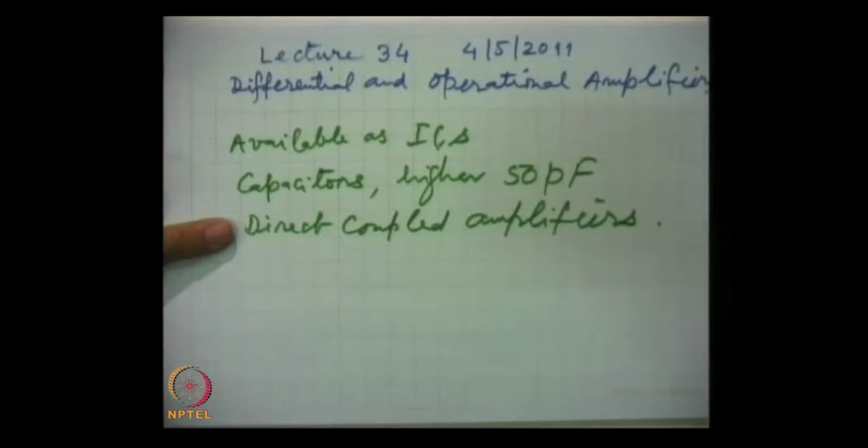And direct coupled, where for coupling just a direct conducting path connects the source, for example, with the amplifier, no need of a coupling capacitor, and hence the frequency response obviously will be different. There is no restriction on a smaller frequency. These amplifiers will work at as low a frequency as 0, that means for DC also they will work equally well as for several kilohertz, a few hundred kilohertz and so on. So these are direct coupled amplifiers available on integrated circuits.